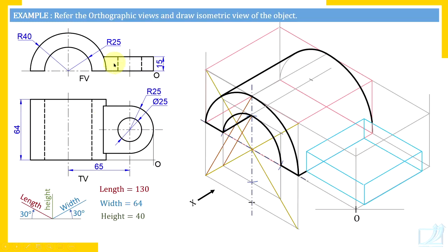Now we'll draw the U-shaped plate. Now this U-shaped plate, its top surface has a U shape. Now how do we construct any shape? I have told you earlier. If you want to construct a shape, first curved edges, then principal edges, and finally non-principal edges. Now here there is a curved edge. It is a semicircular edge. So we'll have to use again the same four center method. That is, we'll have to construct a rhombus first.